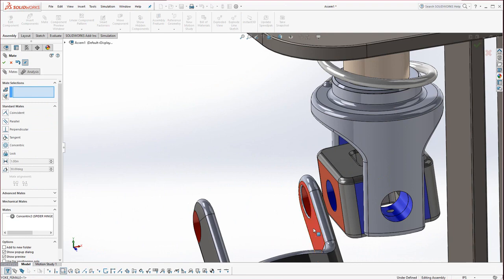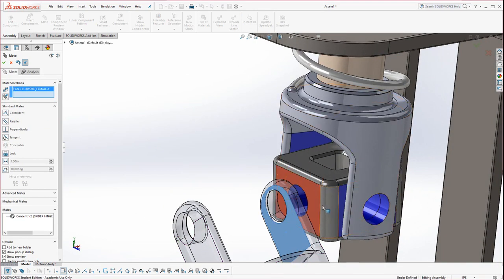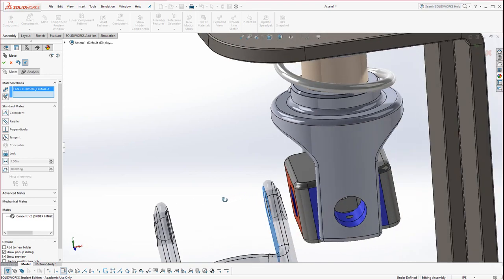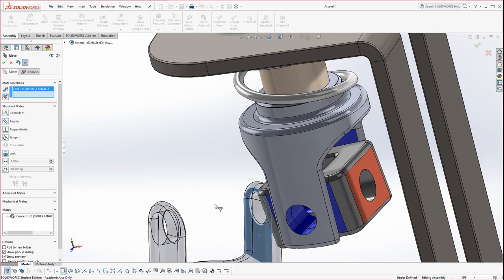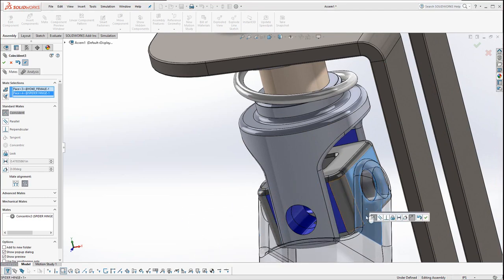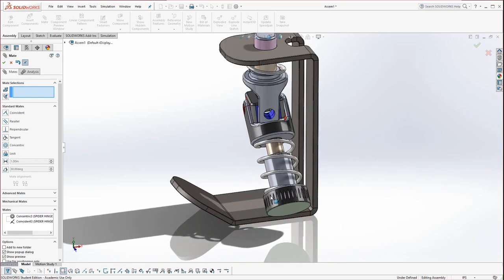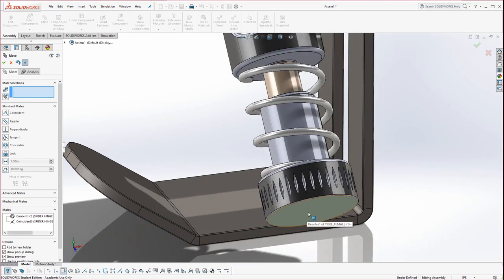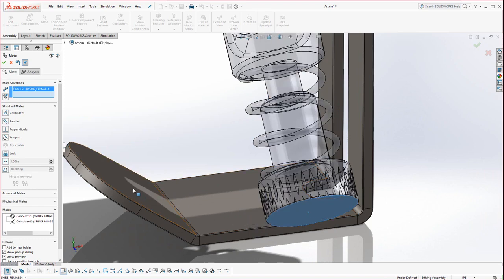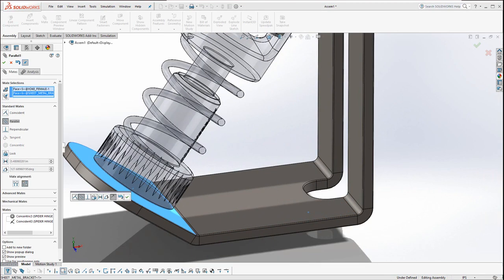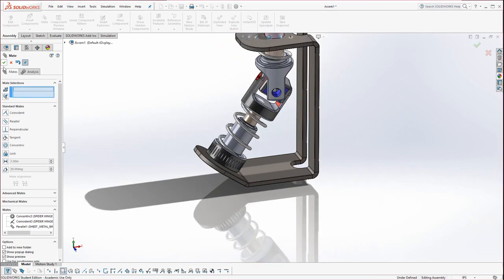Now select this red flat face on the inside of the leg, but don't select this red face that's closest to it because it will remain on the outside. There is a flip switch, but depending upon what you have going on, it might not be the best option. So just select the opposite face, thus it moves the part into alignment the way we wanted it to. Okay, finally you'll see this pale green face under here. Select that face, and then select this face, and it should align itself. And notice what it picked. It picked parallel for us. Hit the green check mark.